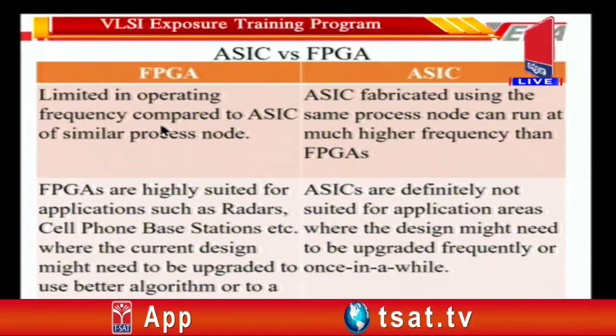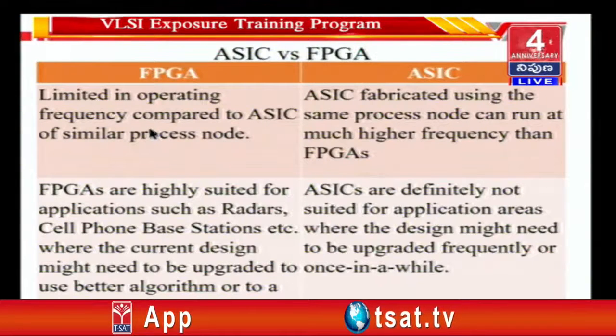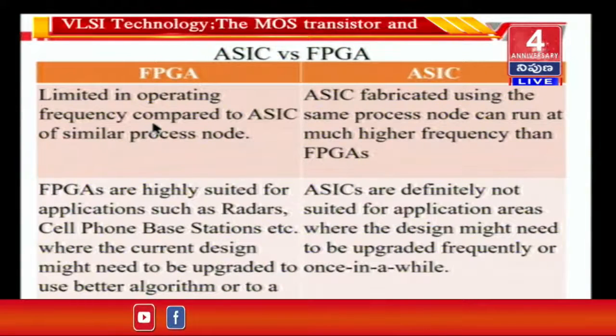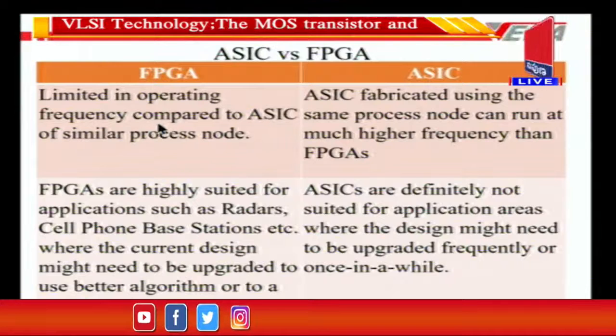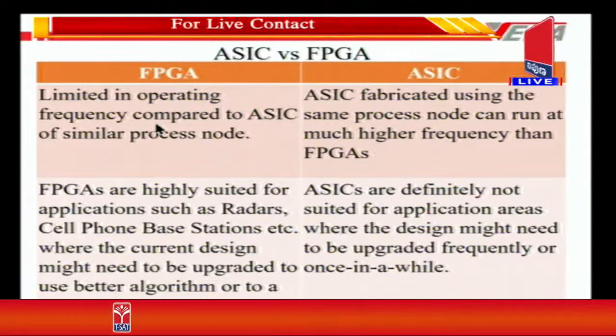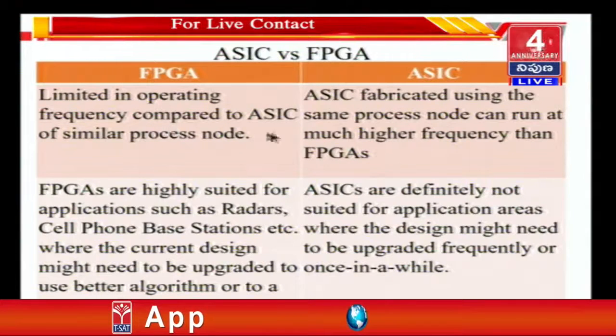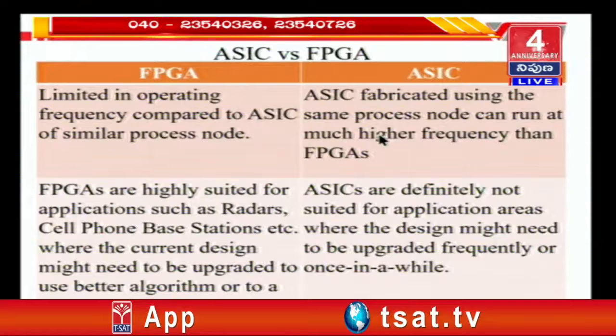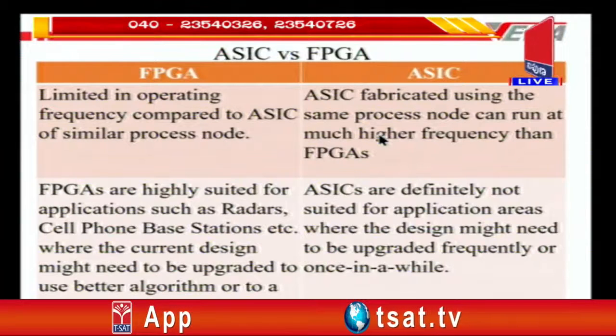Therefore, the routing resources consume a lot of delay in terms of interconnect delays, and therefore FPGAs are limited in their operating frequency compared to ASICs of a similar technology, whereas ASICs can operate at much higher frequencies.